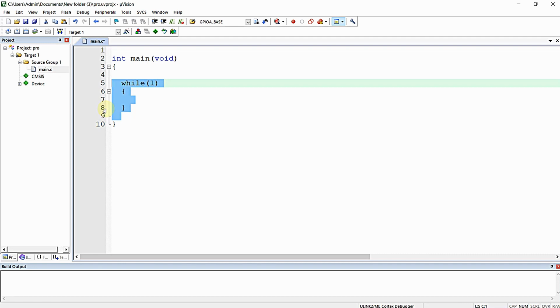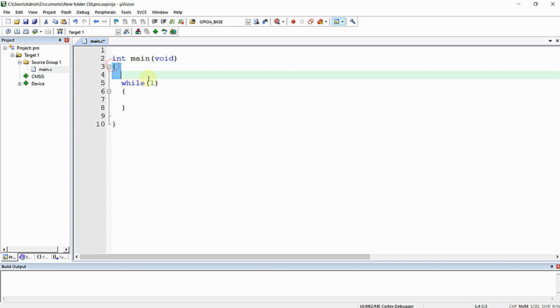This is an infinite loop which will be containing the logical part of the program which needs to be executed again and again until the microcontroller is stopped. And the portion of the program just before the while of 1 inside the main function will contain the configuration lines of the program which need to be executed only once initially. So there are two segments of an embedded program. One is the configuration segment and another one is the infinite segment.